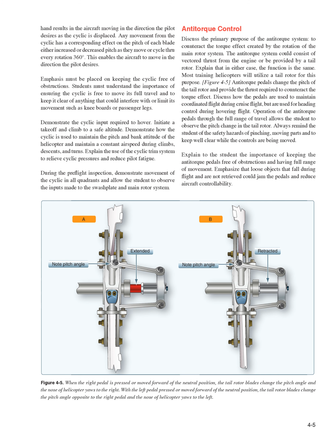During the pre-flight inspection, demonstrate movement of the cyclic in all quadrants, and allow the student to observe the inputs made to the swash plate and main rotor system.